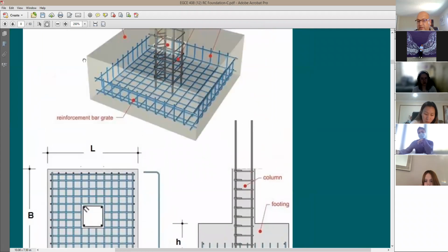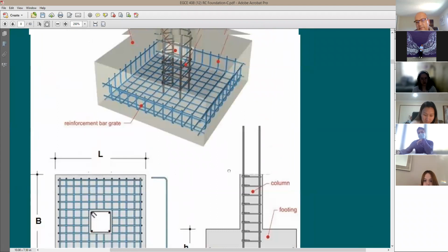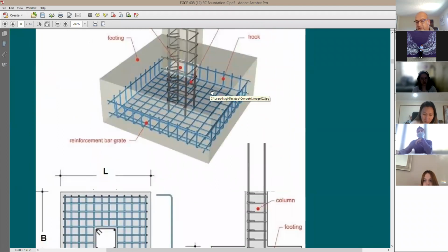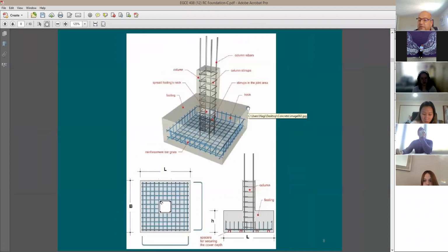Here's a section through the footing. As you see here, the reinforcing of the column and the ties are running through the pad. And then here we go, now we have the reinforcing of the footing. Also, look at the reinforcing of the foundation here with this footing. They go in both directions. And the reason is because of the type of deformation that happened to the pad and the type of moment that you have on it. So in plan view, you are going to see here a mesh. We call this a mesh. It's going to be reinforcing part in both directions.